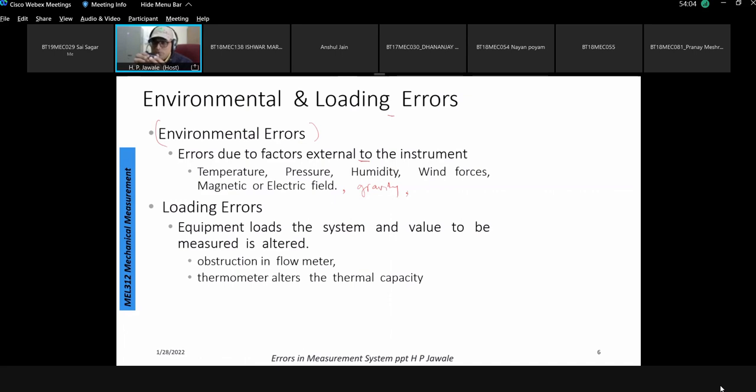And that's what you find: measurement of the density of such elements, which do not have a very solid geometry, becomes very difficult. That is a simple reason. It's because of the loading. It is the input pressure that is applied on the jaws. It is going to compress the component. And if it is rubber or some other element which can be compressed, it will never be able to give the appropriate reading of the true input. So that is loading.